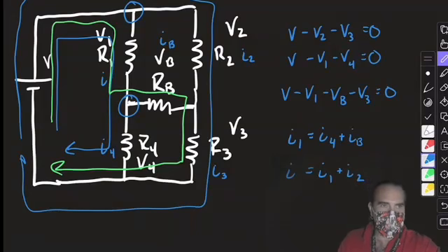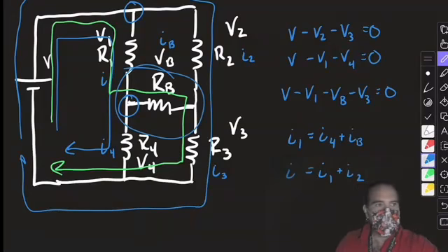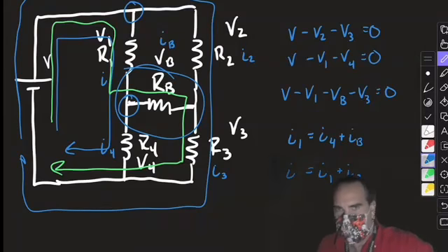Real circuits are complicated. The reason that this circuit has a usefulness is because it's called a Wheatstone bridge. The bridge resistor can be carefully measured for its resistance properties by tuning the bridge specifically for that resistor. It's one way of creating a tunable circuit that allows for precise measurement of resistance. Resistance can be hard to measure because trying to measure it affects the circuit. So when we talk about circuits, there's the circuits that don't fit the mold.